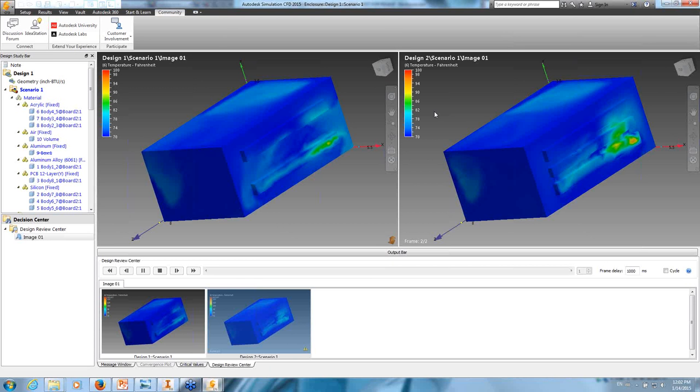Yeah, so a question just came in. I saw Paula respond back about results mode. Can we select by group? You need to set up the groups within the pre-processor first so that it comes over in the post-processor. You can't set up a group in the results because it's brought through from the solver. If you do want to create a group, create it in the pre-processor and then rerun your analysis for 0 iterations, and that will then update that group and have it in the post-processing result side.